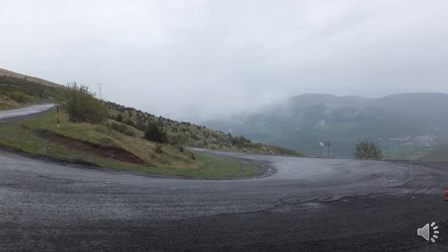If they had a higher amount of bitumen, and also if the aggregate was better graded, it was well graded, that could have potentially prevented it. The other thing that could prevent it is actually having smaller aggregate particles in the asphalt. So if the largest aggregate particles were smaller, then it would have more shear strength. Of course, it would have less skid resistance too, so it's a trade-off.